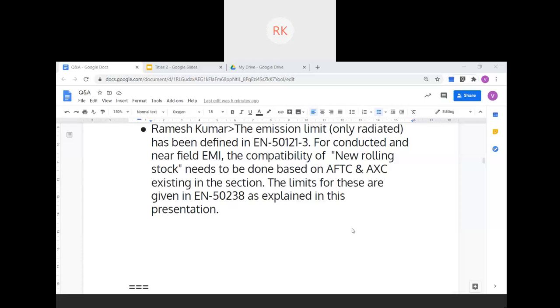Right, sir. I think this is an interesting submission, sir. It has to be taken forward in the right way, because you can actually look at TCAS as a degraded version of ETCS level 2. And therefore, you can have something like a switching balise just before it enters the TCAS territory. And as Yadav says, the switching balise now gets the OBC ready for a degraded ETCS level 2.